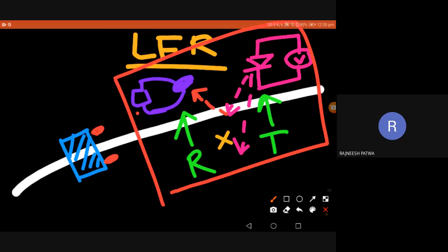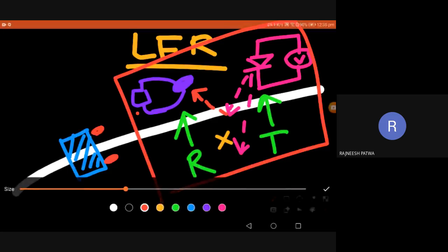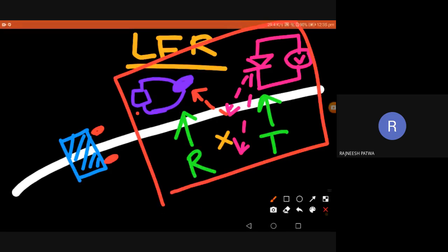On a white surface, my receiver is always getting reception back, and the receiver will give me output equal to one. That means I am over a white surface. I am getting a reflection, so my receiver is giving me high output.